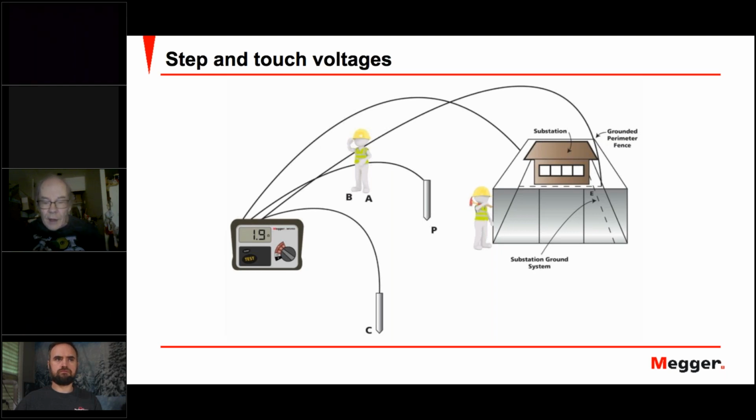Well, the reason for that is because there's so much ground, it's everywhere. So the currents that get put into the ground, they even out over an enormous space. And so you're outside walking around, you're not getting a voltage gradient between your feet. But if you get close to a substation, then the danger starts to rise, because as the fault currents go back to the substation where they came from, then of course the concentration of current is going to rise. So the substation needs to be protected.